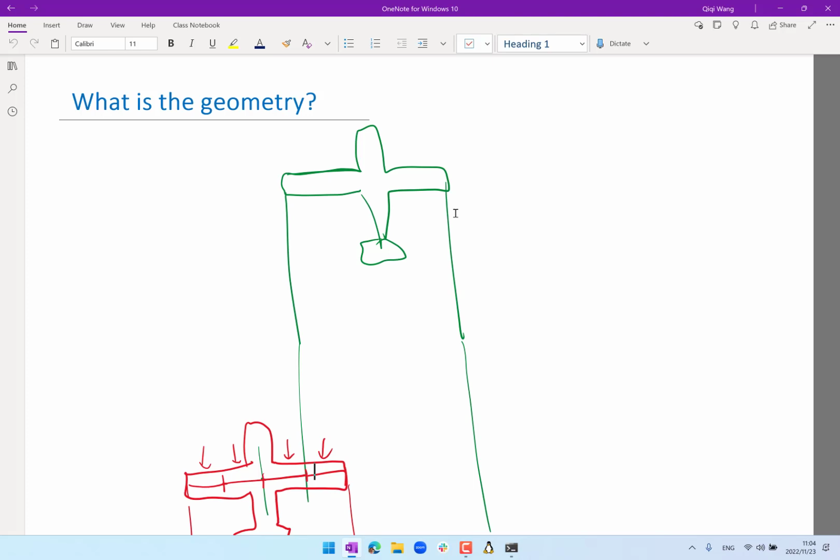Maybe today I'm going to talk about the induced drag, because that seems to be the hardest part of the calculation, right? Finding the power essentially requires you to multiply the total drag with speed, and finding the energy involves basically multiplying the total drag with distance. So both are pretty simple if you can figure out the total drag.